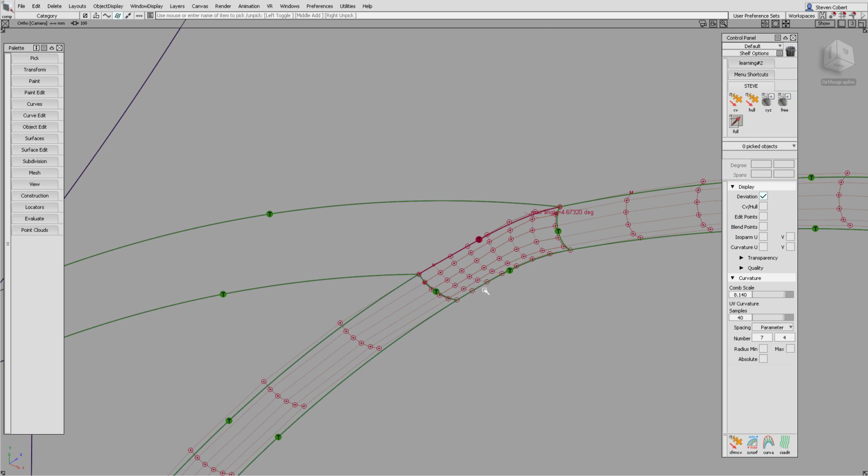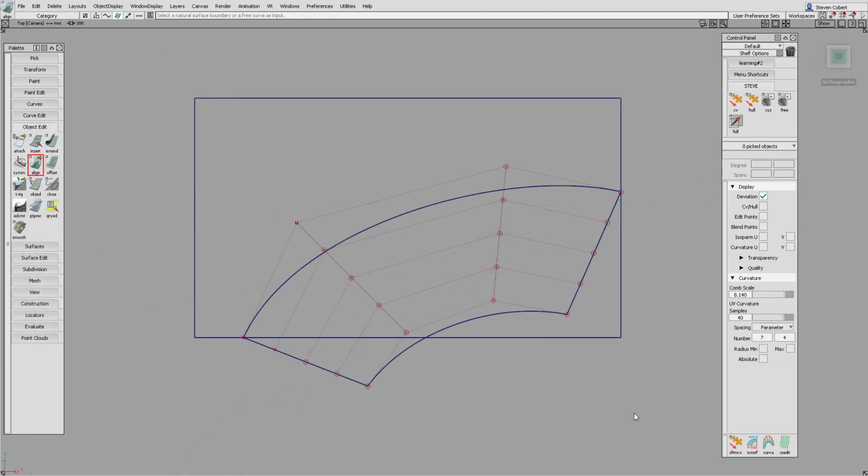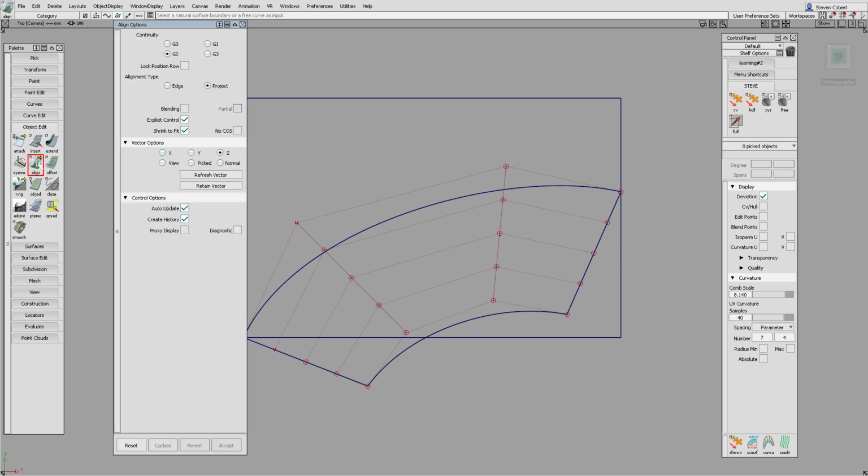So often the solution is to split the surfaces instead. For example, like here, where we've had to split these surfaces to form very thin surfaces at the ends. Now this may not be ideal, but because the fillets are very small, then it really doesn't matter. It's more important to get everything to align than to worry about the highlights on a fillet that may be 0.5 millimeters in radius.